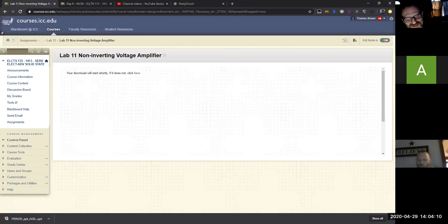They're very widely used for active filtering, because most filtering is done with these guys because their response is very quick. And that's the thing with hysteresis and stuff, when you have a passive filter. So let's say I set up a passive RLC filter, if you will. It's waiting to respond, waiting to react. And in the case of inductance, you have that phase lag, and it's lead and lag, depending on if it's voltage lag or current lag, depending on if we're dealing with capacitance or inductance.